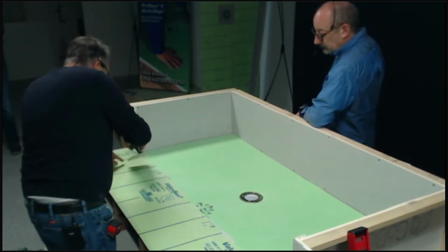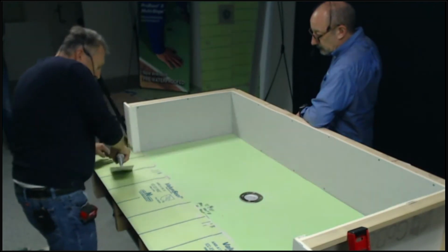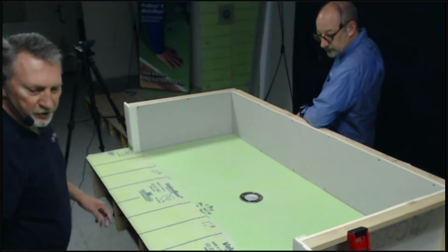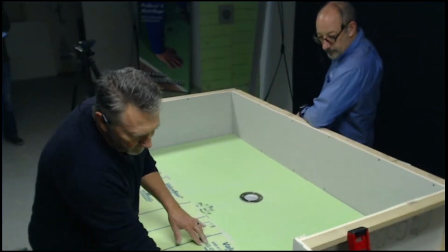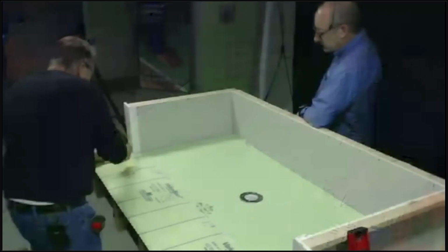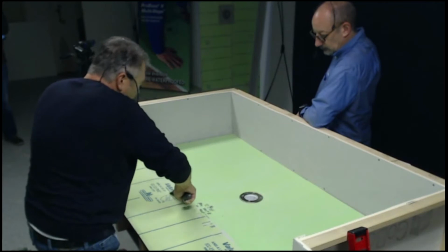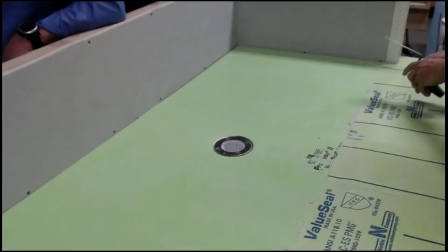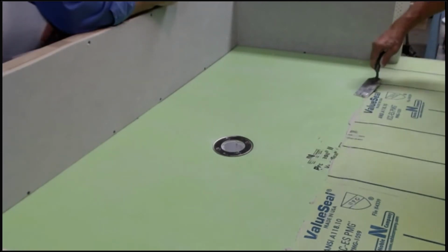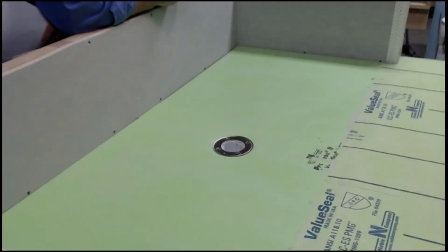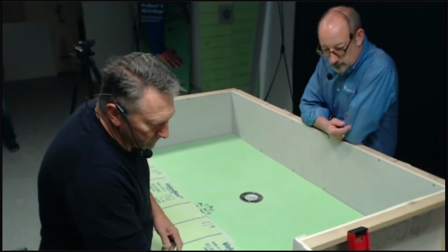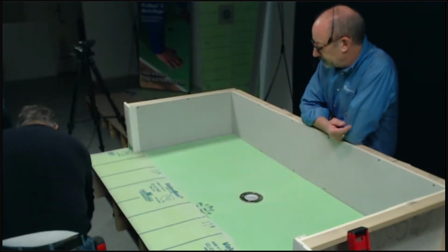If I have a spot that I can see right here, make sure that you just tool it in. Okay. I'll take my margin trowel. I'll tool in my little wing walls here, and I'll tool in my 2-inch overlap into my dry space, to create a shingled overlap seam. Just remove the excess. Simple as that.